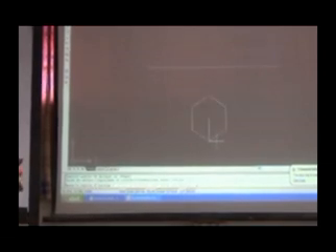I am selecting this object. So still I am smaller. I am going to draw it again. Second, that is 6 sides. Enter. Specify the center of the polygon. Center. Enter the option inscribe, I. Specify the radius. I am giving 15. Enter. So whatever dimension you want, you can draw whatever geometry you want.